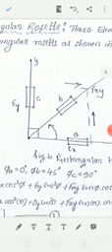I can also say the first one in the horizontal direction is gauge A, gauge B, gauge C. Similarly I can write epsilon A, epsilon B, epsilon C, right? So this one I can say epsilon A, epsilon B, epsilon C, so x, y, and this one in between. Now similarly I can also write the orientation, that degree.